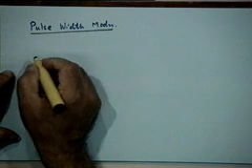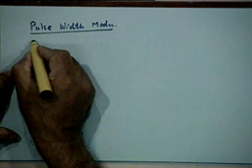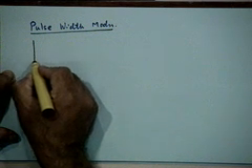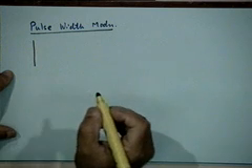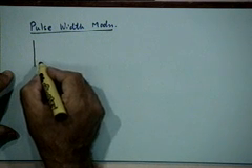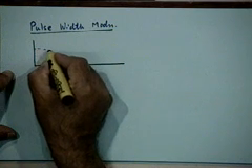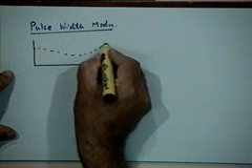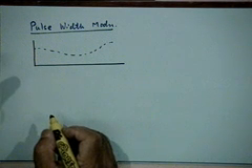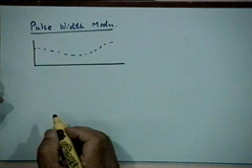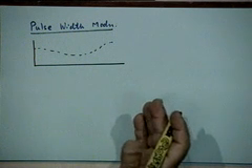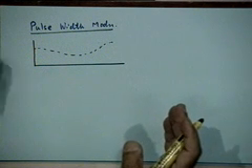Let us just go through a series of pictures which will illustrate one way by which you can generate a pulse width modulated signal. Let us say you have a message signal like that. To start with, you generate a PAM signal, a pulse amplitude modulation signal, which is very easy to generate because all you need to design is a sampler.